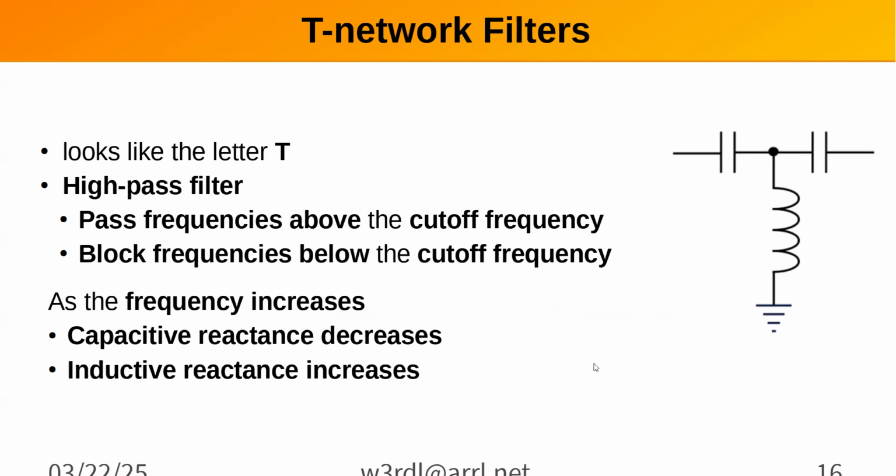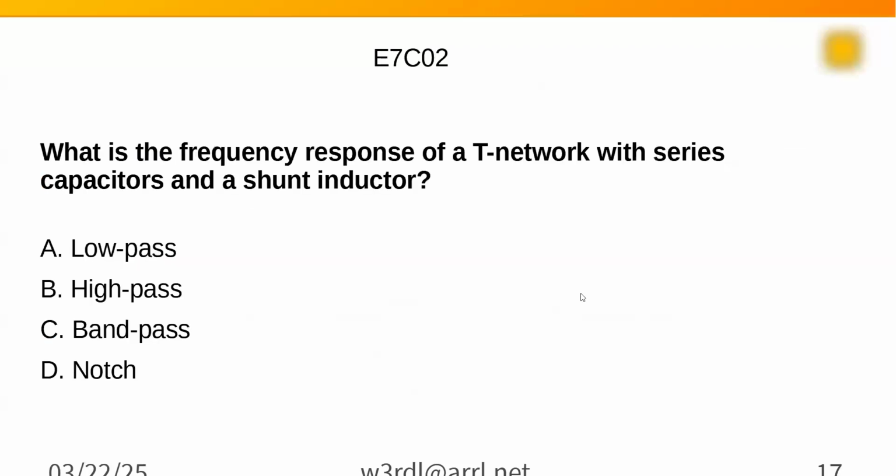And in this case, it's going to look capacitive at the lower frequencies and inductive at the higher frequency. So that's the same as a series RLC circuit, if I can remember them right. When you operate it above its resonant frequency, it becomes inductive. High pass, B, Bravo.